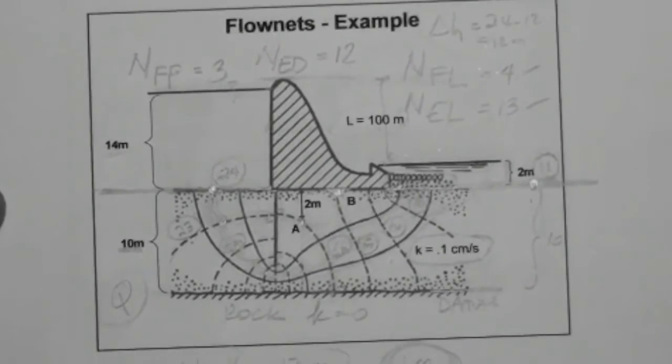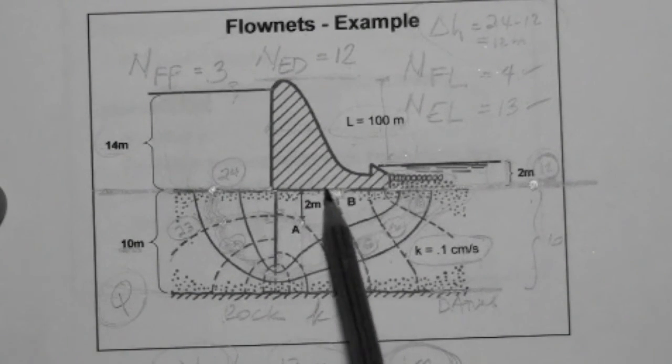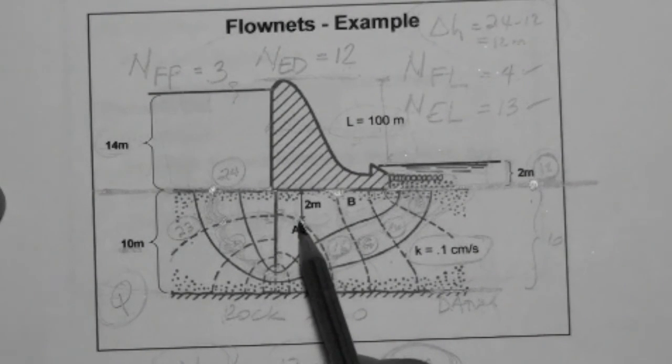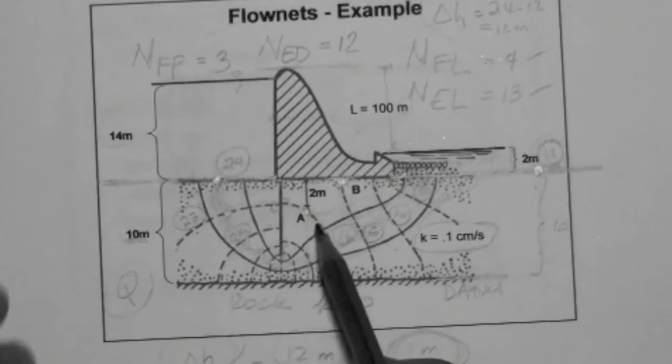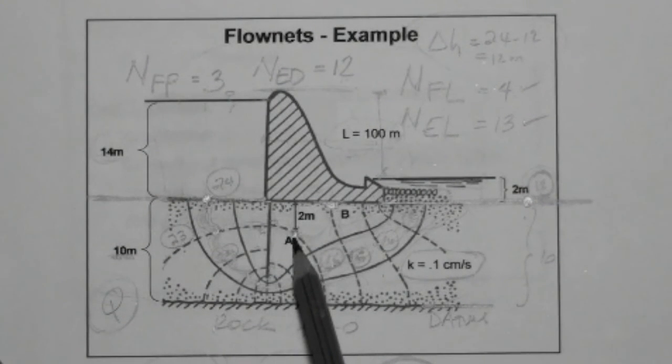The pressure obtained at this point, that we got as 49 kPa, is an uplift pressure because it acts at the surface between the soil and the structure. The pressure that we got here, 78.5 or so, is just a pore pressure like any other. It's not an uplift pore pressure. Okay.